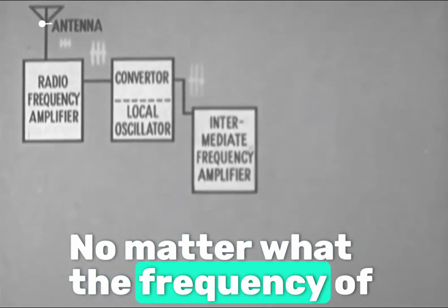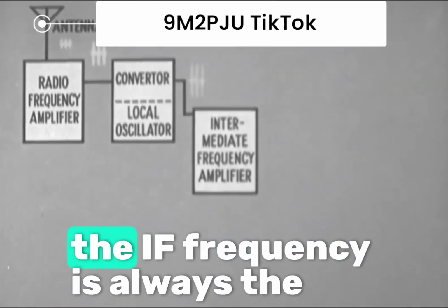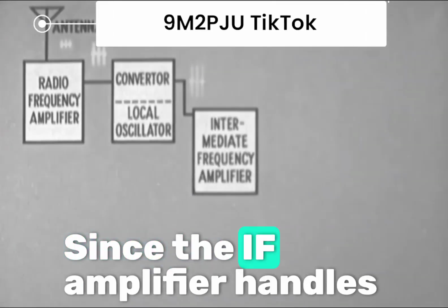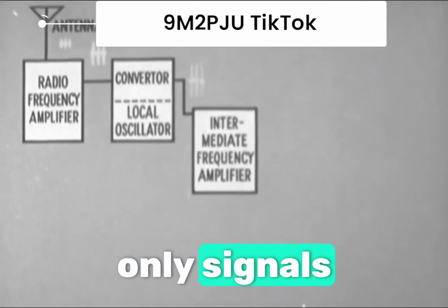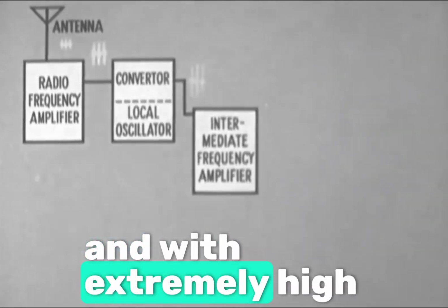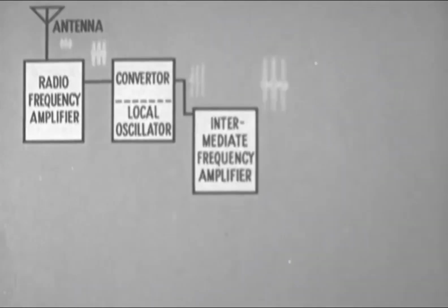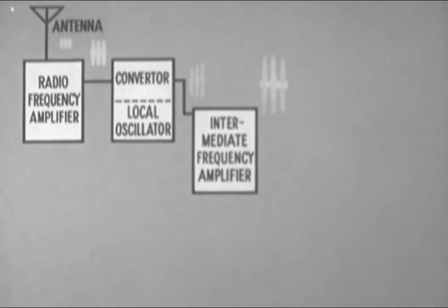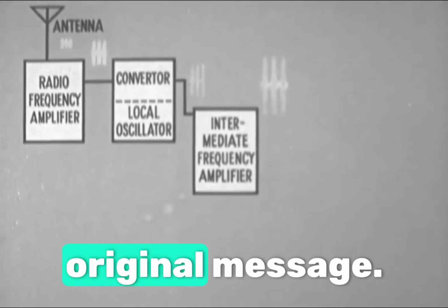No matter what the frequency of the received signal, the IF frequency is always the same. Since the IF amplifier handles only signals of this frequency, it can be made very efficient and with extremely high gain. Although the carrier frequency has been changed, the carrier envelope has not, and it still contains its original message.